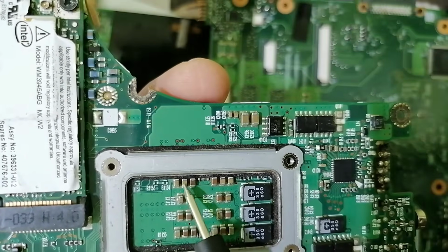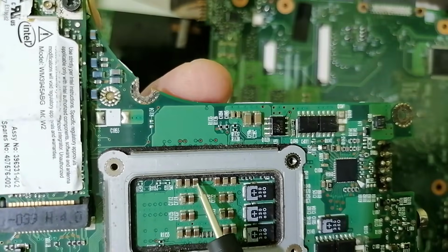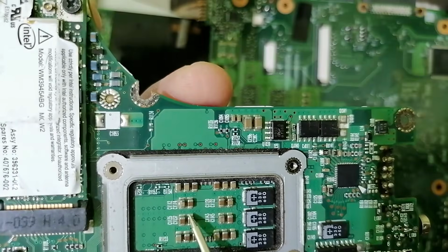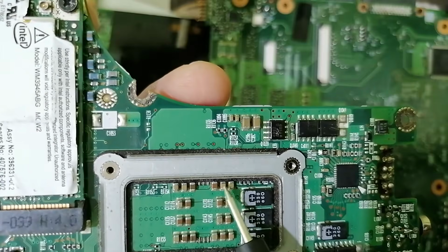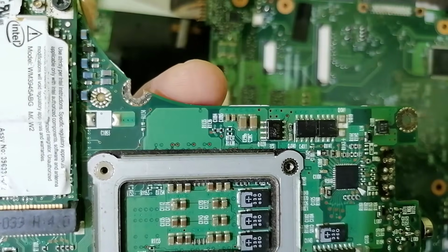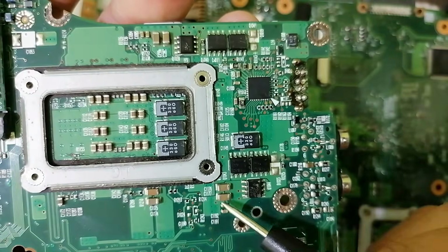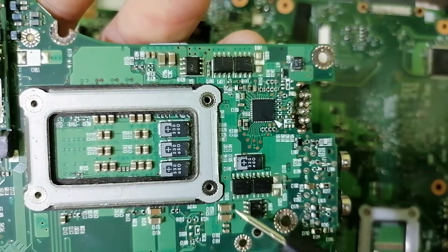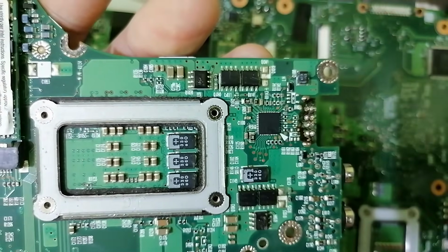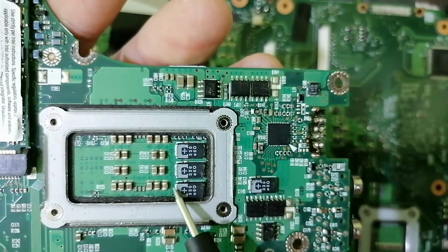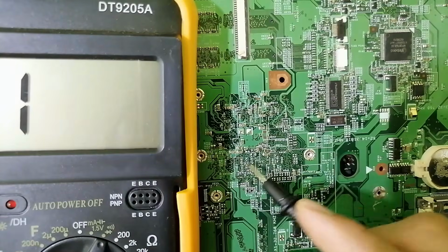Those over here are also not the same as this one. So if this one has failed, do not replace it with this one or this one. You should replace it with another one. For example, these two are the same. These two here are the same. This one, no. So this is how you can replace ceramic capacitors. Here also, if this one has failed, we can replace it with another one of the same size and same color. But do not replace this one with this one. So over here we have many ceramic capacitors.